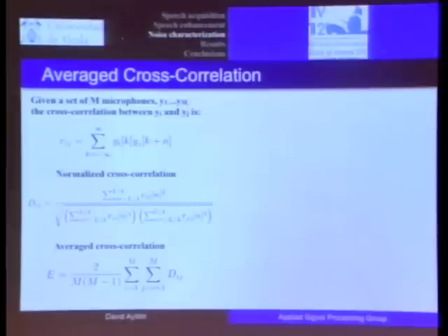Well, this can be calculated in the time frequency domain. When we work with speech, we always work in the time frequency domain because we cannot analyze a long period of speech signals at the same time. We have to window the signal. So this correlation function can be approximated with this simple expression in the time frequency domain.